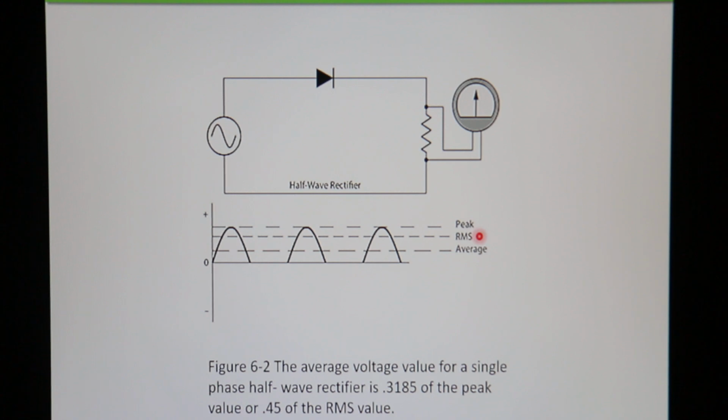And as a matter of fact, guys, these AC meters that you have, those are RMS meters. When we read a wall circuit, that meter is reading the RMS voltage. That's not as much voltage as is in that wall. It's much higher, actually somewhere around 169 volts. That's the peak. But RMS stands for root mean squared.